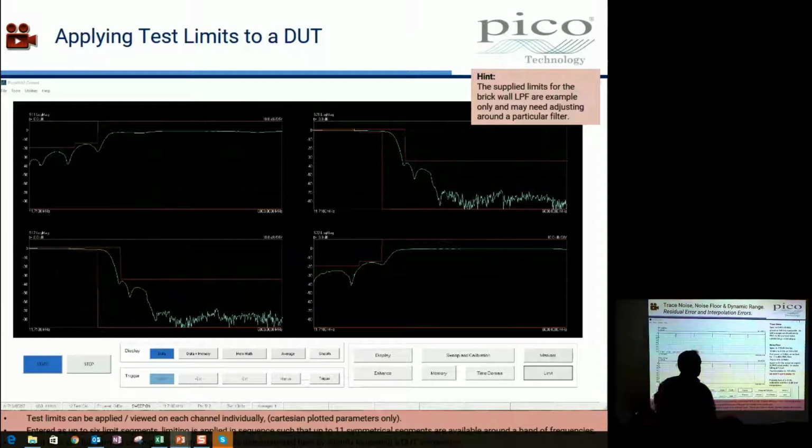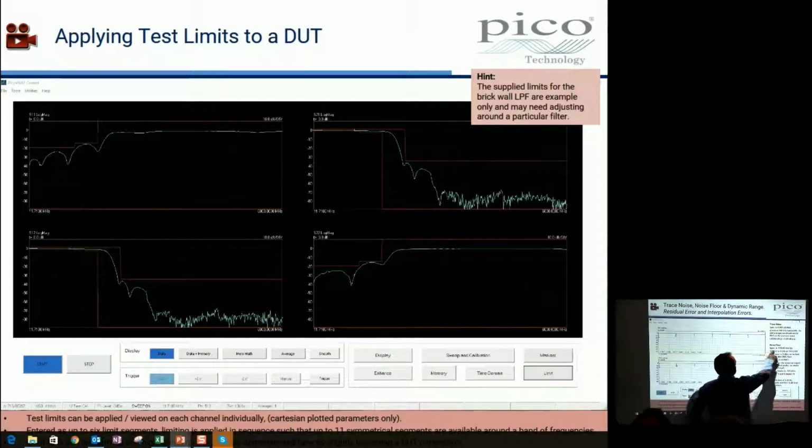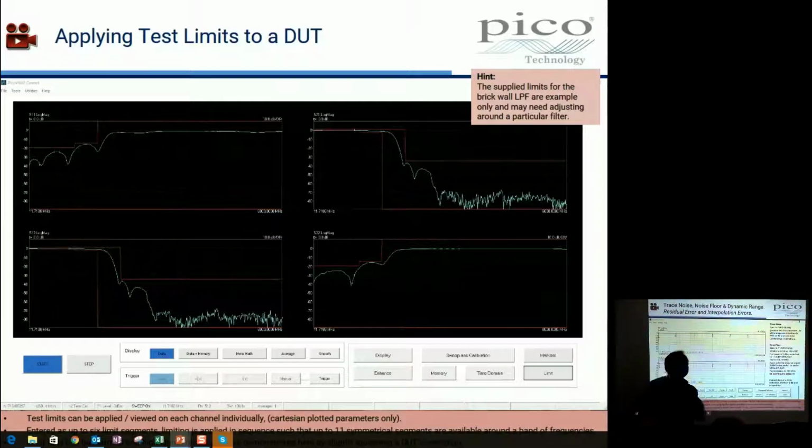Oh yes, and just a reminder here, this noise floor, 118 dB RMS typical, that's in the bandwidth 1 megahertz to 4 gigahertz. We are allowed to go slightly out above 4 gigahertz, and it's at 10 hertz bandwidth. So you have to do this as a rather slow process, which we'll demonstrate.